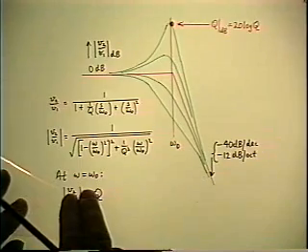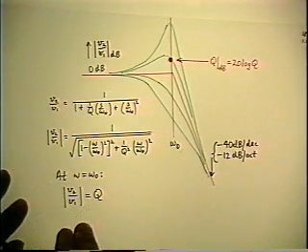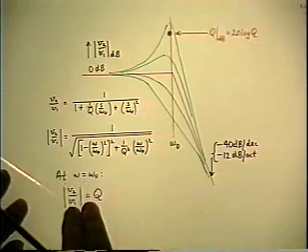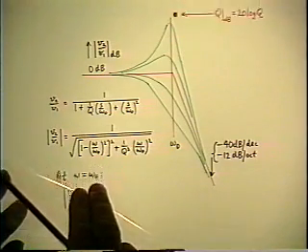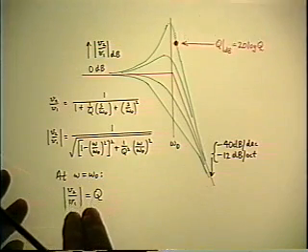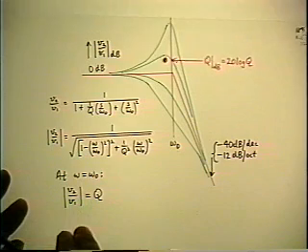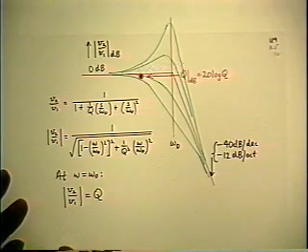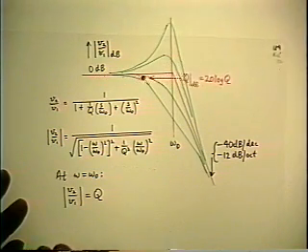Notice that the value of Q is not the maximum. The maximum is a little bit to the left. If Q gets to be very large, then the maximum becomes essentially the value of Q, but for lower values of Q, the maximum moves to the left a bit. And when Q is getting close to 1, actually that maximum moves so far to the left that it disappears off the picture, because when you get a Q of less than 1, there isn't a maximum.